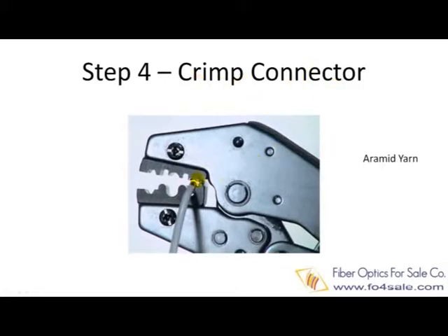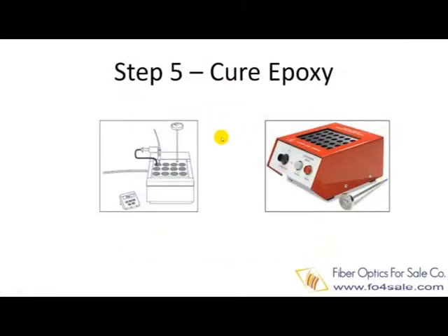The bare fiber strand is inserted through the back of the connector and into a special matching fluid that closely matches the index of refraction of both fiber pieces. The result is that the usual deflection of the incident light rays that would occur at an angled fiber end is essentially absent. Instead, the beam passes into the matching fluid and then into the fiber stub with virtually no refraction, eliminating a very time-consuming step from the assembly process.